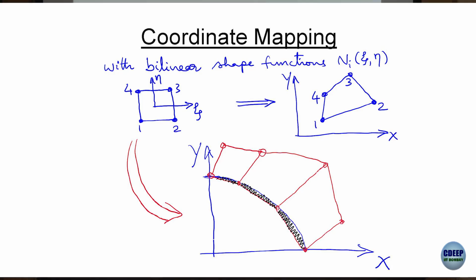So if you are trying out a simple problem, a geometry whose volume you would know, otherwise you can check the finite element model against it. As you increase the mesh, see how it actually approximates the original. This becomes critical for systems when you have very complex objects being analyzed.